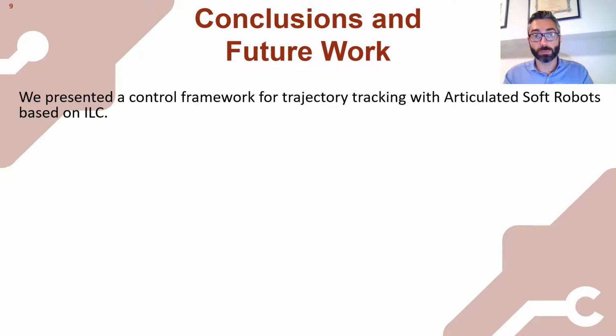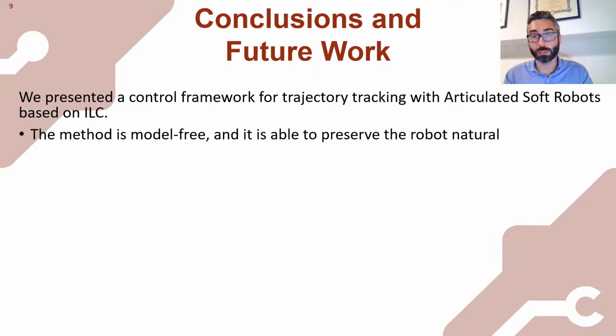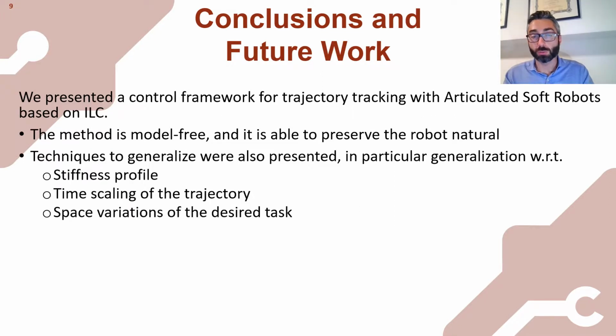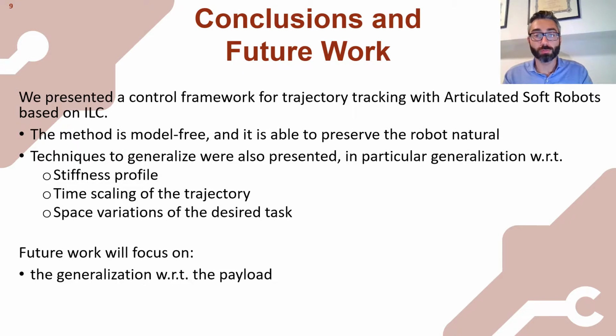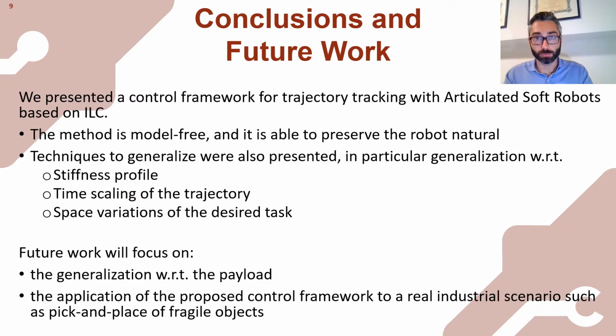To conclude, I presented a control framework for trajectory tracking with articulated soft robots. This control framework is based on iterative learning control. It is model-free and it is able to preserve the compliance of the system. I also presented techniques to generalize the previously acquired control action, in particular with respect to stiffness, time, and also space. Future work will focus on the generalization with respect to the payload and also the application of this control framework to a real industrial context.